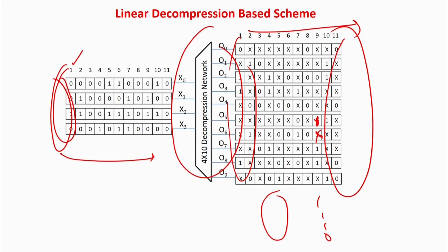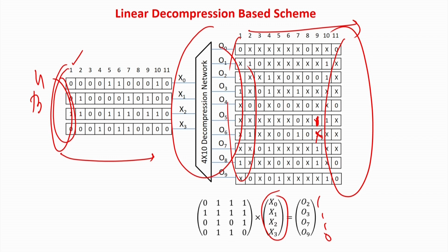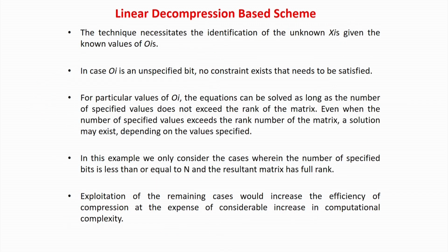So it tries to find out, okay, I will only have 3 channels and this is the pattern required. I find out that there does not exist any linear circuit to do that. So either I can use 4, or I can somehow modify the test pattern so that it becomes compatible. So there are a lot of iterative, heuristic based algorithms to solve the problem. Now a slightly more theory I will tell you on when it is possible.